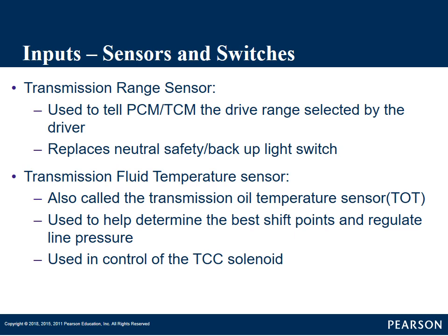On non-electronic transmissions, this was always a separate switch. Now we can incorporate that into our range select switch, our range sensor. It also has circuitry in there for our backup light switch.